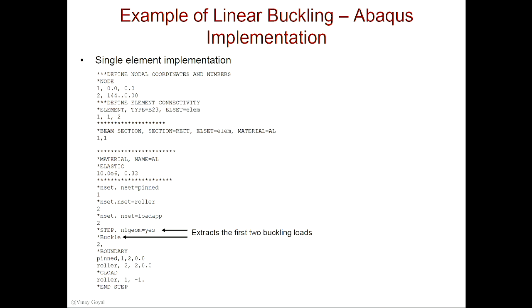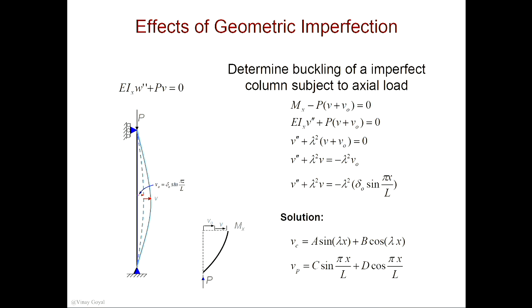So that is the load when this beam will buckle. Okay? Let's assume we put an imperfection into this structure. So let's start with some small imperfection. If I put a small imperfection, and let's assume it's a sinusoidal imperfection, sine of pi x over L, I should have said x over L. So I have an imperfection that goes along with that. With an applied load P, the governing equation is this. This should be a double derivative here, so I need some corrections.